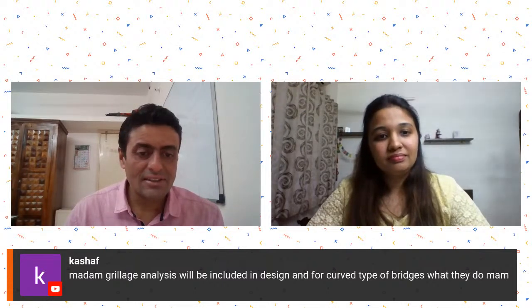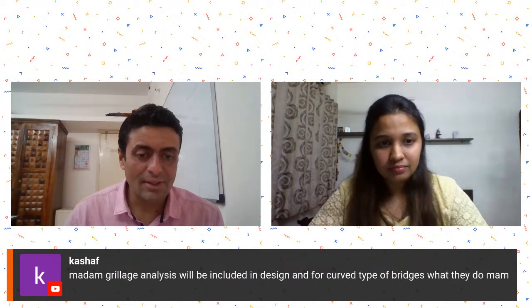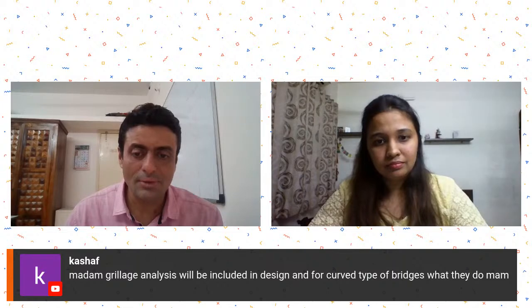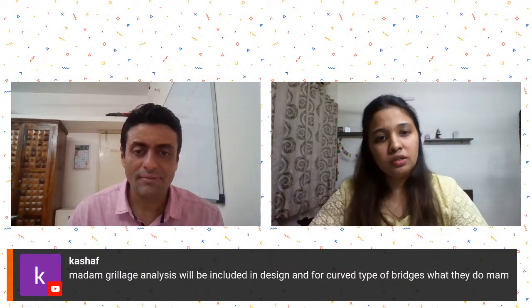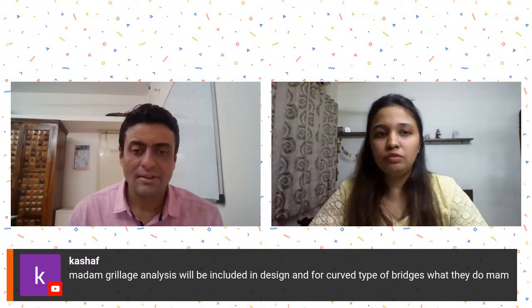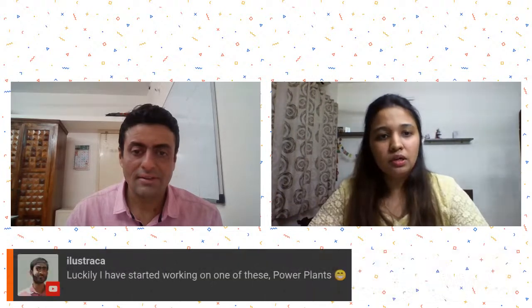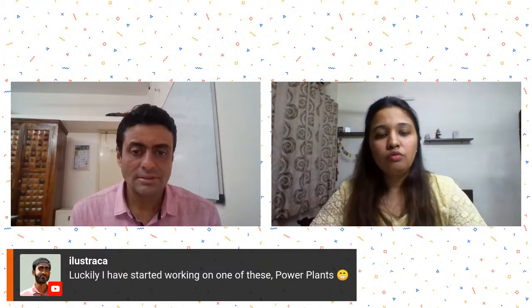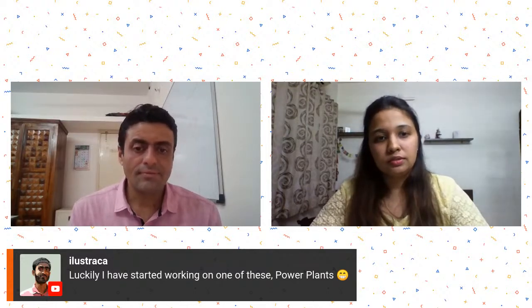Kashaf is asking, will grillage analysis be included in design, and for curved type of bridges, what do they do? Curved in plan, I think most of the times, for a very simple structure, we go for line analysis, 2D analysis. Otherwise, for every structure we do the grillage analysis itself.